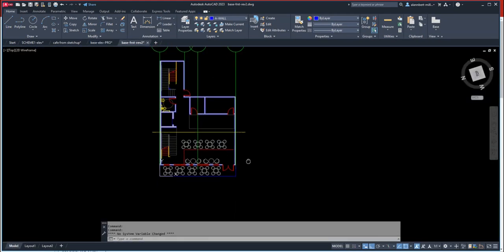Where do you want to cut the section? You want to cut the section usually where the stairs are. Okay, so you want to cut the section here all the way here, like that, straight up. And so that's my cutting line. This is my cross section, and I want my longitudinal section over here.